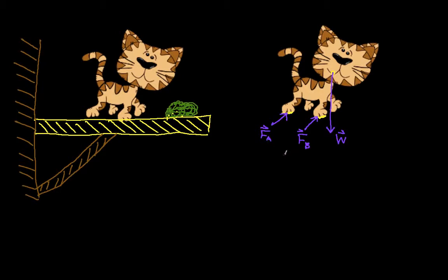Now, one of the things that you'd be tempted to do at this point is to start applying your knowledge of statics or dynamics and trying to figure out what these forces are doing. But you want to wait until you've actually drawn the free body diagram to start thinking about statics or dynamics. You don't want to worry at this point what you expect to be true, because your goal is to just define the contact points and those forces at the contact points, as well as any forces due to gravity. Okay, so we have now the free body diagram of our cat walking on the beam.